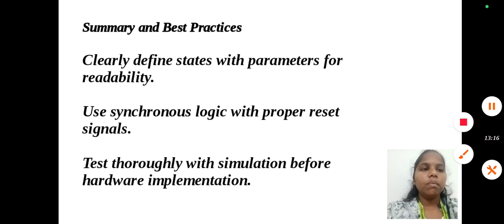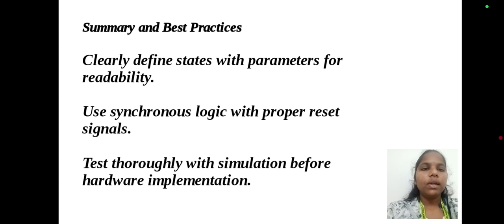Summary and best practices. Clearly define states with parameters for readability. Use synchronous logic with proper reset signals. Test thoroughly with simulation before hardware implementation.